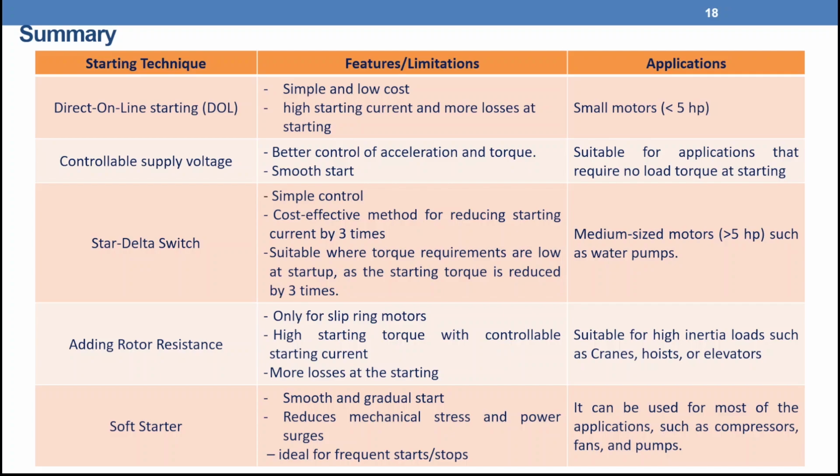So you can use the controllable supply voltage technique, which gives better control of acceleration and torque. We have a smooth start. But we have a limitation here. That one is suitable for applications that require no load torque at starting.